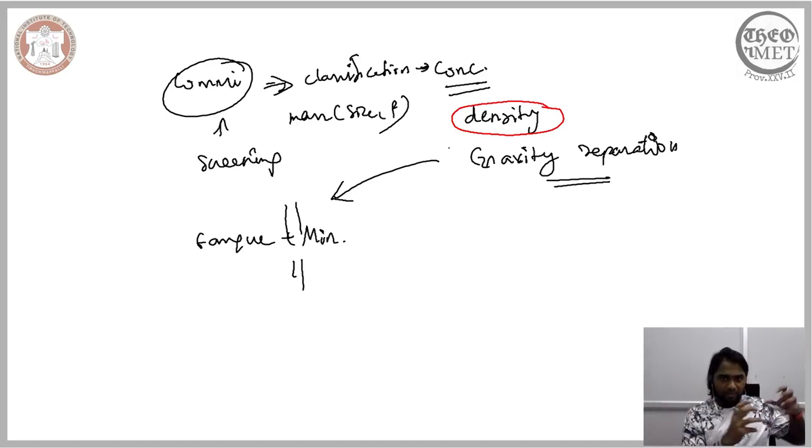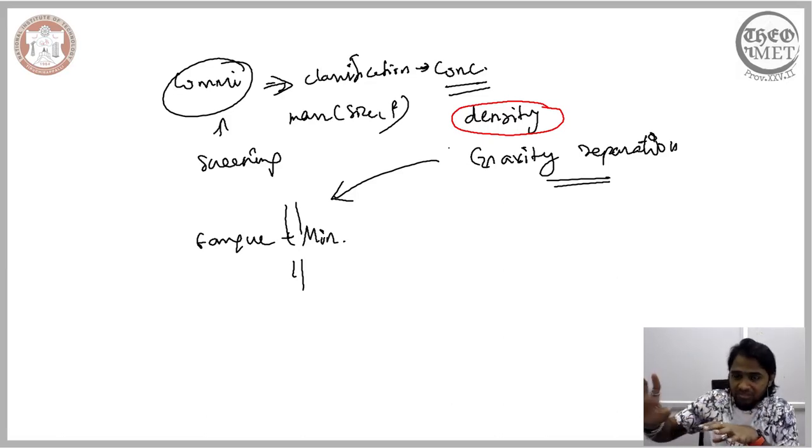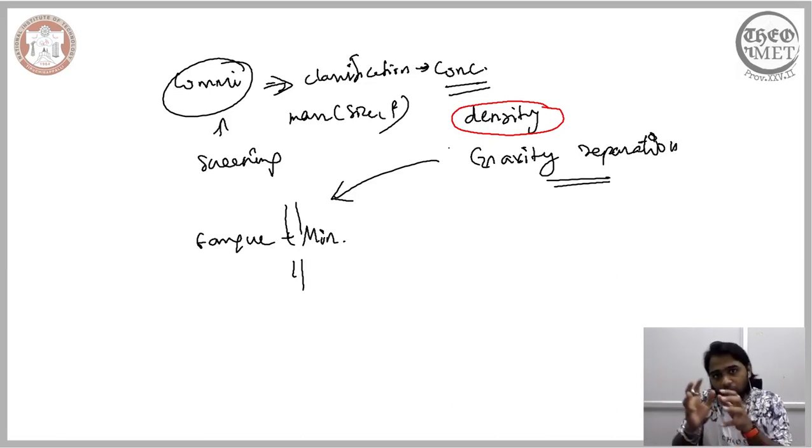So we saw that it is possible for us to have a smooth transition from combination to concentration, but we are not speaking about all the processes involved in concentration. We are restricting ourselves to a specific process of concentration, that is gravity separation. Gravity separation can only be imposed efficiently when the difference in density between gangue and mineral is significantly high. Towards the conclusion of the previous lecture, we saw that there are certain advantages of adopting gravity separation when compared to other concentration techniques.